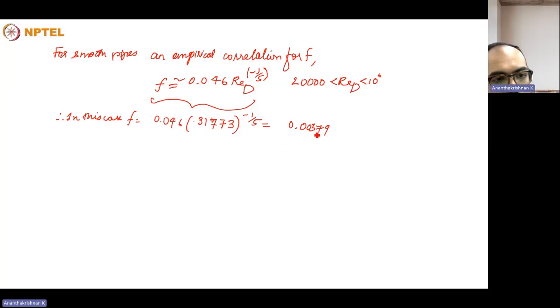So at higher Reynolds number, the value of the friction factor reduces, but it doesn't mean that the friction reduces, because actual friction will be dependent upon the friction factor, the velocity, and density. Velocity is high in this case, and because of that, the actual friction might be high as well.